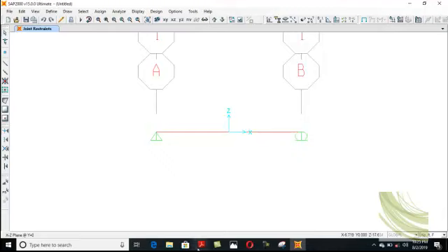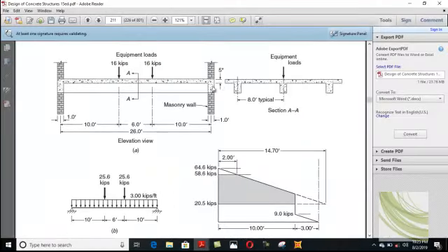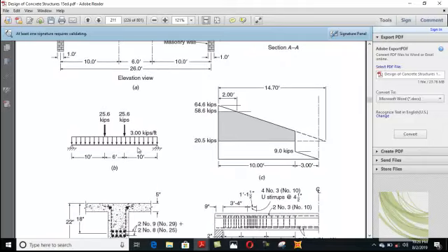You must know that you have to assign these supports, although there are beams on the level of the slab, where the slab is placed on the wall. So these beams, although these joints may be assigned like fixed support, here they are assigned basically simply supported. Clear?